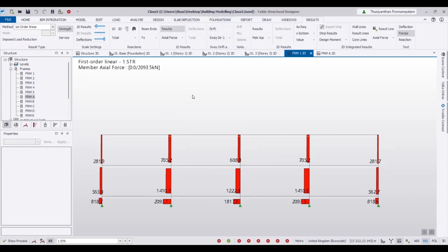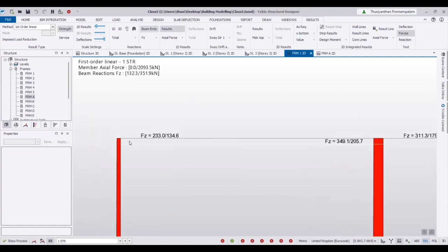Okay, so in case you are doing the steel design, you are supposed to know the beam end results, because when you do the connection, you want to know how much force is transferred from beam to column. The beam end results you can also see here. So if you click Beam, Fy, basically say Fy, you can see here how much is the force.